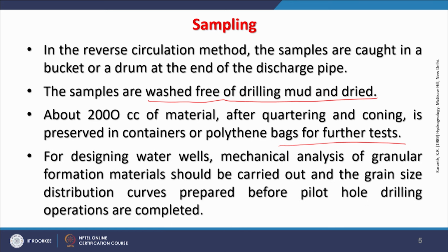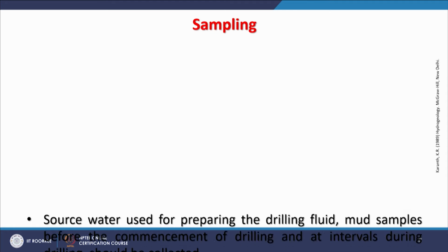And for designing of water wells, mechanical analysis of granular formation materials should be carried out, so that we would like to know what it would yield. It will yield the grain size distribution, and when we measure the grain sizes of the different sediments or pieces which are coming out, it will give us a curve, which is prepared before pilot hole drilling operations are completed. These things are done almost in near real time, so that the information being collected is used and the next step is taken accordingly.